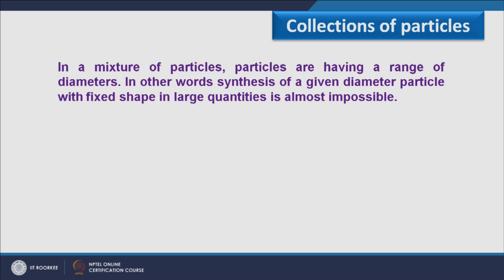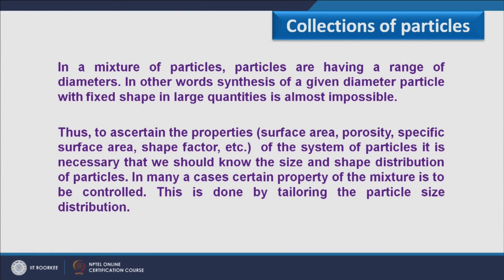In a mixture of particles, particles have a range of diameters. In other words, synthesis of a given diameter particle with fixed shape in large quantities is almost impossible. Therefore, to ascertain the properties such as surface area, porosity, specific surface area, shape factor, etc., of the system of particles, it is necessary that we know the size and shape distribution of particles.